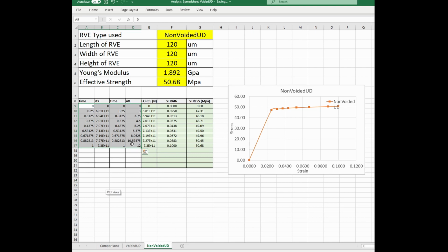What we are trying to do basically is use the reaction force in the x direction, or one direction, and the displacement in that direction. So the force will be exactly that same force. What would the strain be? The strain would be basically the displacement divided by the original length in the x direction, which is the length of the material. I've already indicated that here.